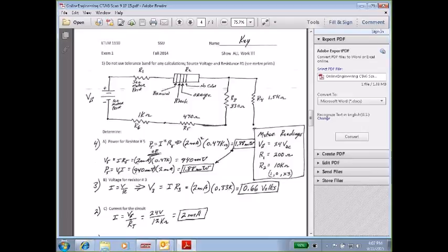And then I spend quite a bit of time dwelling with them on what current is, what voltage is, and what resistance is. Voltage and current are not the same thing, even though a lot of people tend to use those two terms interchangeably. Current is the flow of electrons through a conductor, and the voltage is the electromotive force or pressure that's causing it to flow. And then resistance is our opposition to that current flow. Resistance limits the current that flows through a circuit.